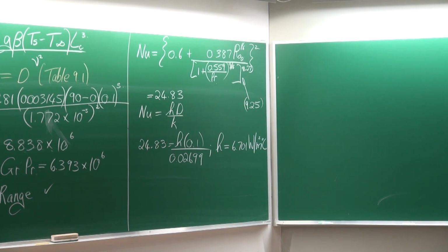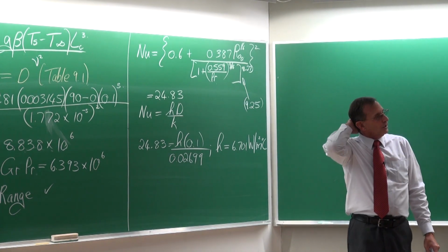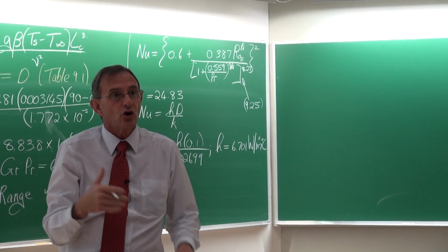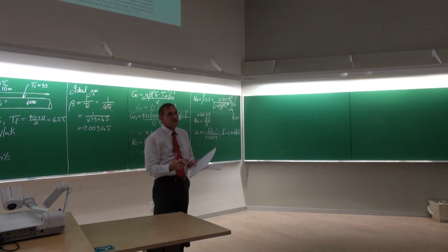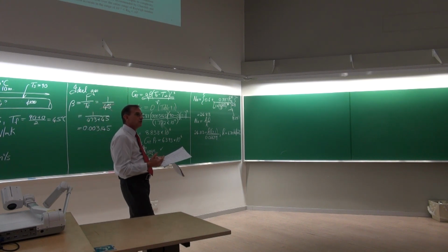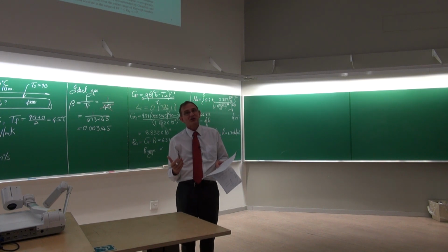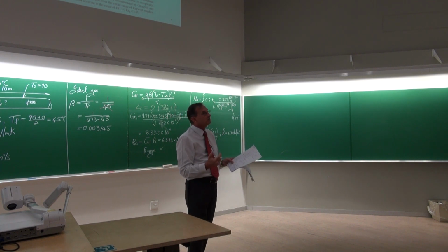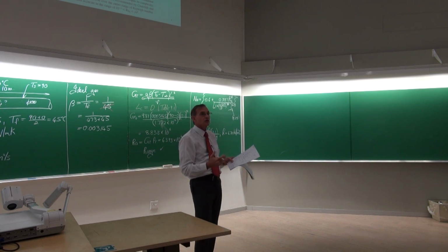It's also quite important that when you start doing all these calculations, you take a look again at chapter 1, where the concept of the heat transfer coefficient was introduced the first time. They said something very important, and that is that in natural convection, the heat transfer coefficients are normally low. Typical order of magnitude is about 10. Then when you've got forced convection, typical heat transfer coefficients are of the order of hundreds to 1,000.